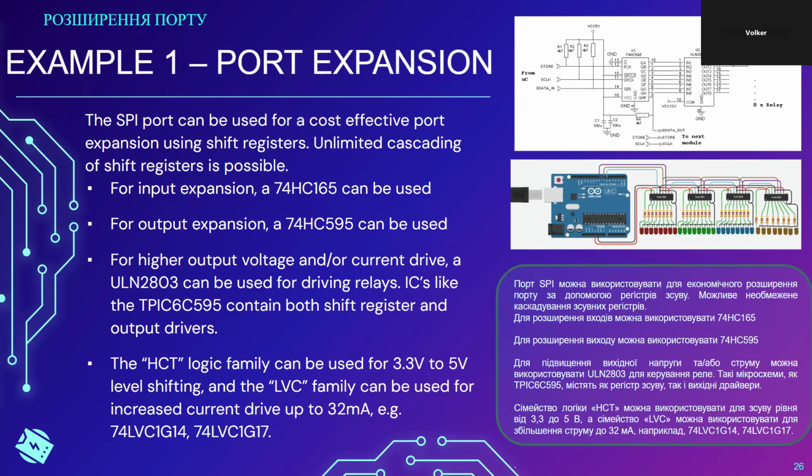It's not uncommon for even cheap microcontrollers to be running at 80 megahertz, at 160 megahertz. In addition, they also have a whole range of tools that can relieve the core processor of unnecessary work, of unnecessarily moving data around. One of these tools is called DMA, direct memory access.